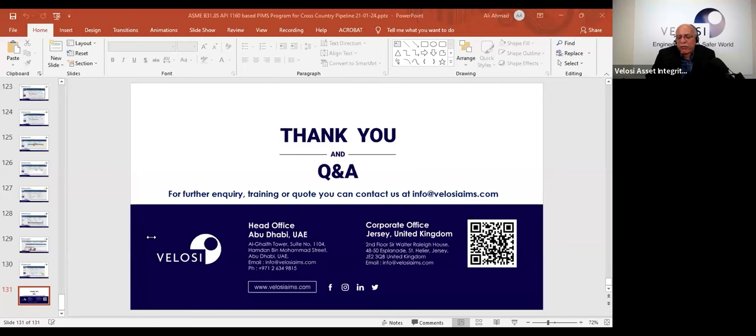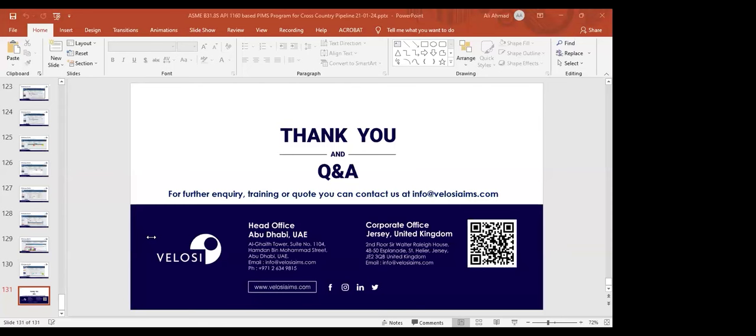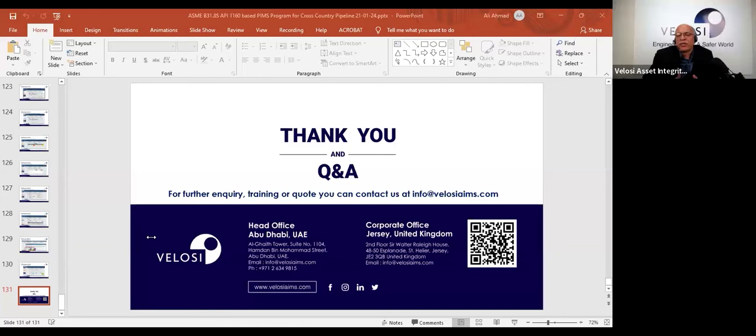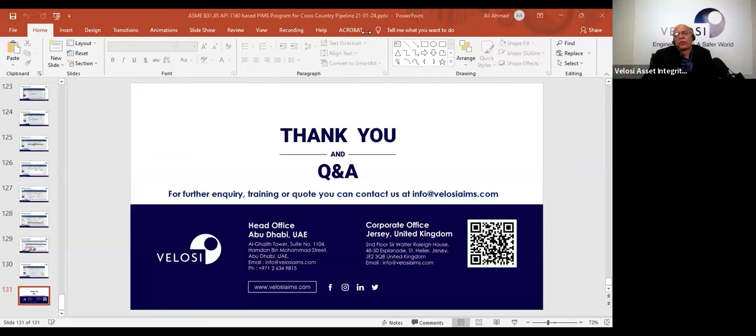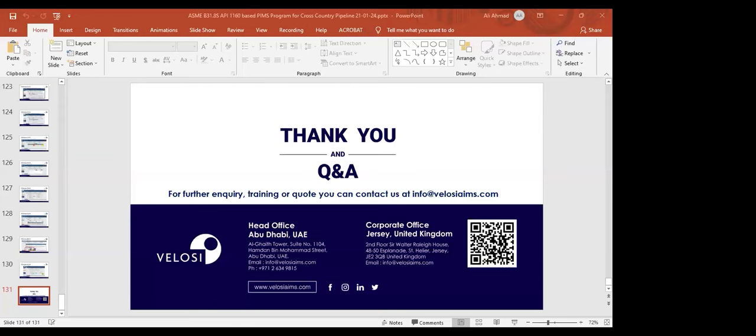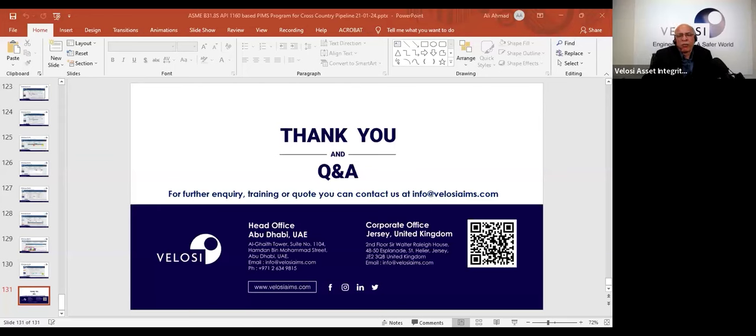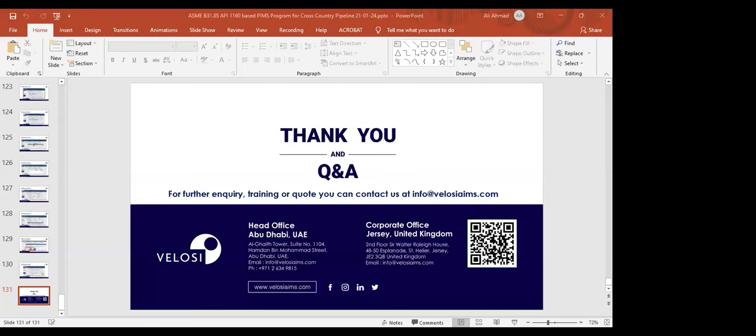And then you gather information, you try to identify all the damage mechanisms and threats, and then you develop the inspection program. That is my whole presentation: how to set up a pipeline integrity management plan. So you need to go through the full presentation we have given today, and you may also refer to API 1160 or ASME B31.8S, which can give you complete guidance.